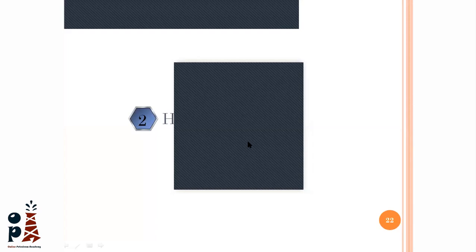Okay. If it is an exploration well, we call it a wildcat well. Why? Because we don't know what we are going to have. So in the exploration or wildcat well, we have to install the diverter, which is used before installing the BOP. In case we have shallow gas or a sand lens and there is a kick or uncontrolled fluid flow, we have to divert it away. And in case we are already using the BOP, we have to close the well, calculate the kill mud weight and use a higher mud weight, because if we don't do this, we cannot continue drilling. So we have to increase the mud weight to face this overpressure.